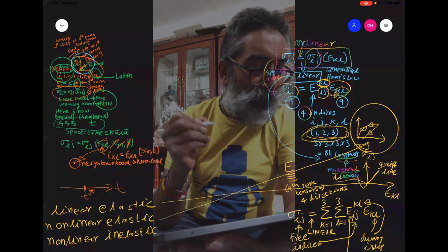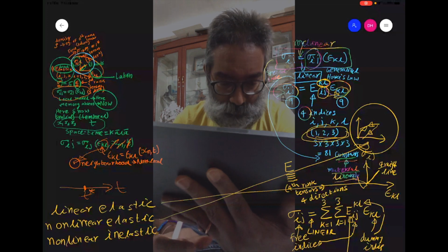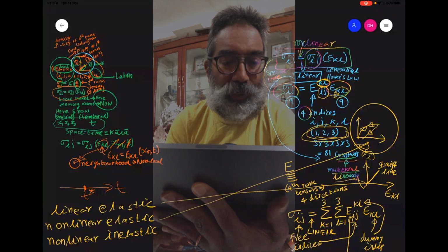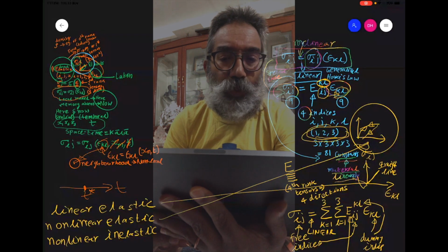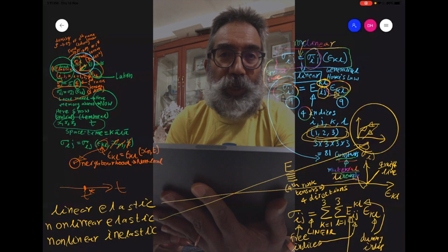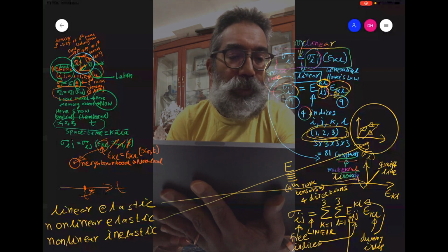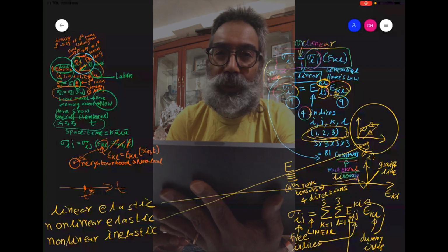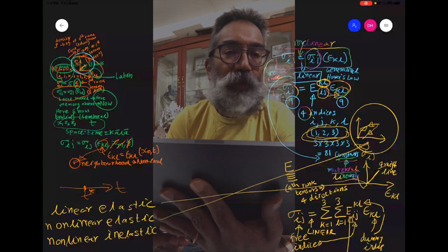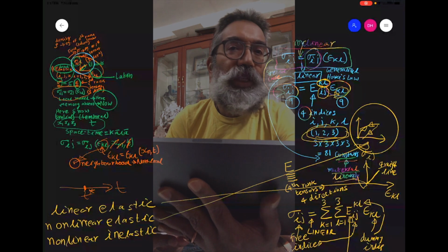Okay. I mean, even the linearity is only a part of a small loading and unloading curve during the tensile and the compressive. That's right. And that is good enough for most materials that we deal with. Even though they are going through very large deformations, the strains still remain well within the material failure limits, which for most composites would be of the order of 2% or so before they have a brittle fracture. And therefore, within that limit, you would always see that the stress strain curves are linear.